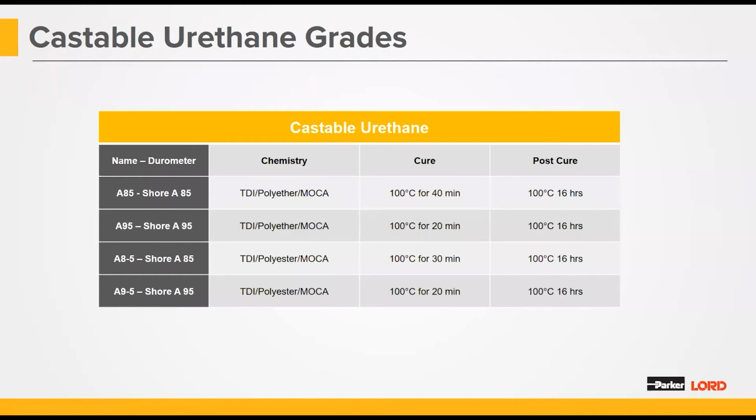Now, it's very important that the post-cure is included, because if you don't do the post-cure, you won't get your final performance parameters for your parts.